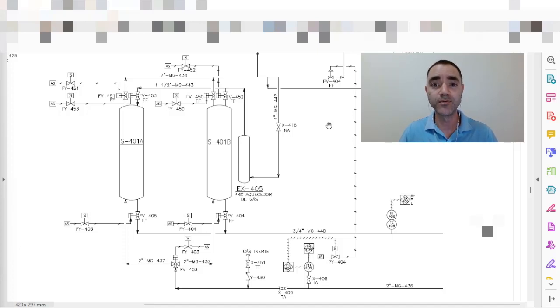But on the other hand, you will not reduce the OPEX or the electrical power required to do the production in the same proportion. So when you design a plant at design conditions and you run your operations at lower rates, most often it means that you are spending more energy to produce the product, and the KPI will be lower, and that is not good for the profits of the company. Why am I telling you that?